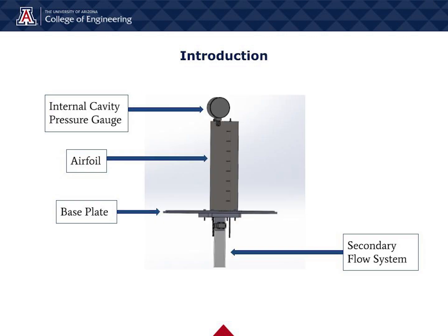In order to address these problems, our team designed an additively manufactured compressor inlet guide vane with fluidic separation control. To achieve this, we used computer-aided design software, or CAD, to create an aerodynamic shape called an airfoil that had similar aerodynamic properties to an IGV and allowed for the injection of pressurized flow into the primary flow over the airfoil. In order to assist in the design and verify the parameters of the design, finite element analysis, or FEA, and computational fluid dynamics, or CFD, analyses were performed.